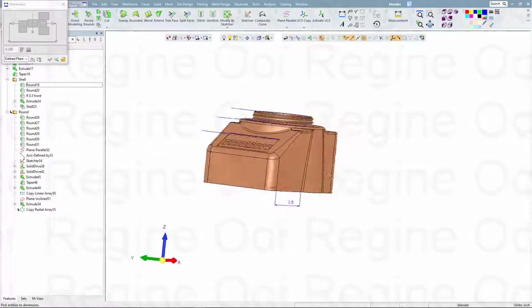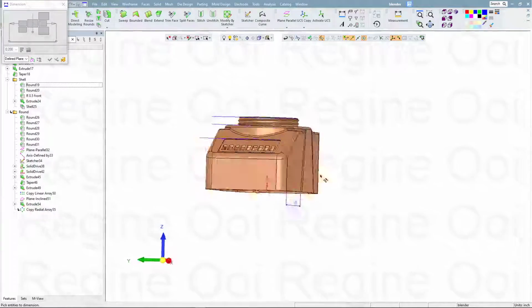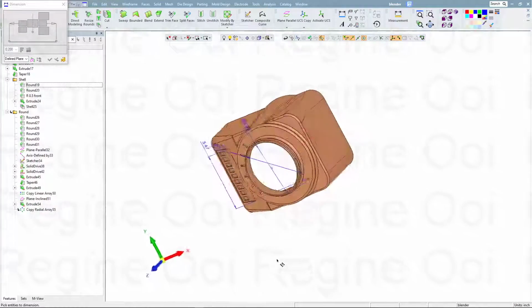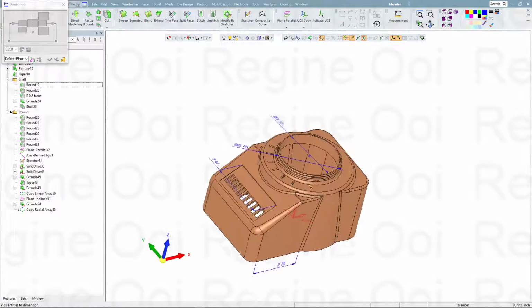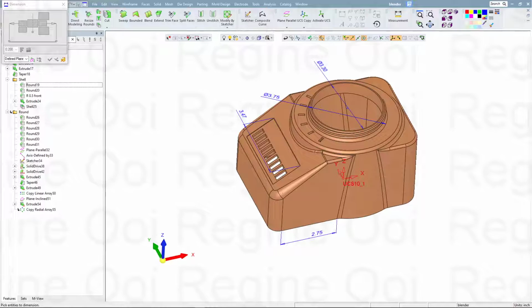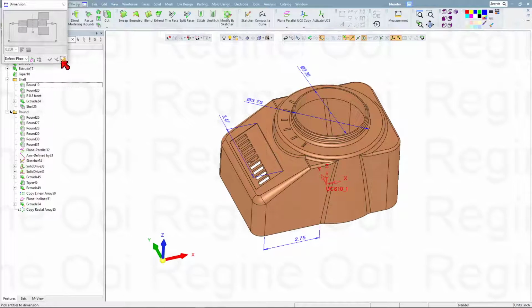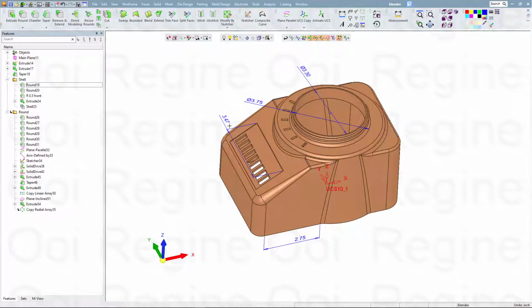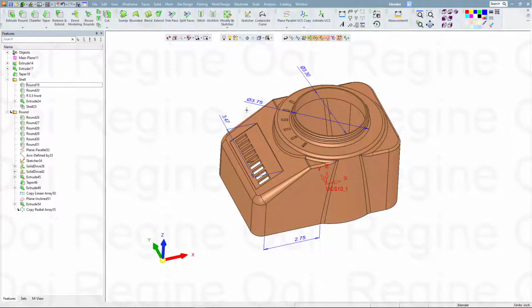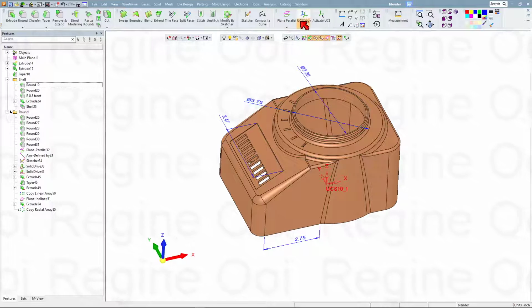This is the 3D dimension. Okay, so if I set the PMI dimension over here, after I'm done, I export it to 2D drafting. This dimension value is also available in drafting PMI.